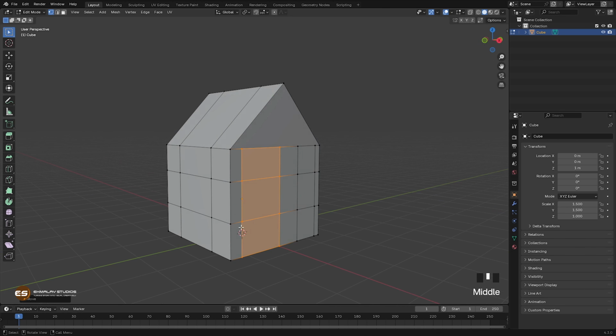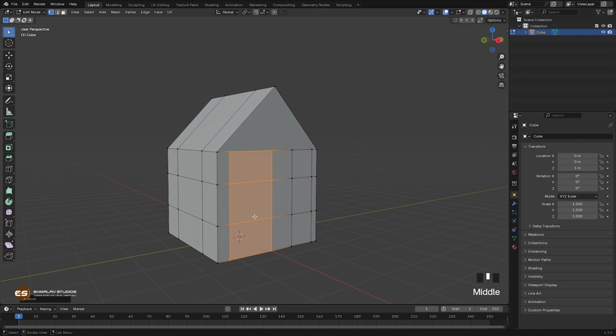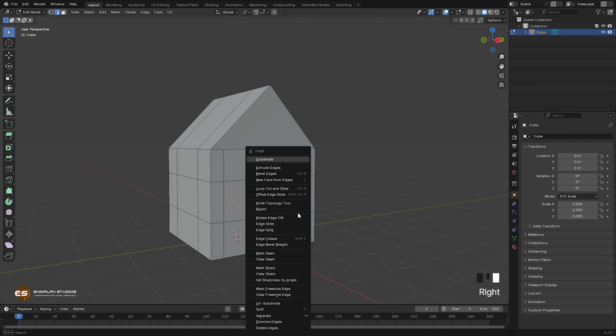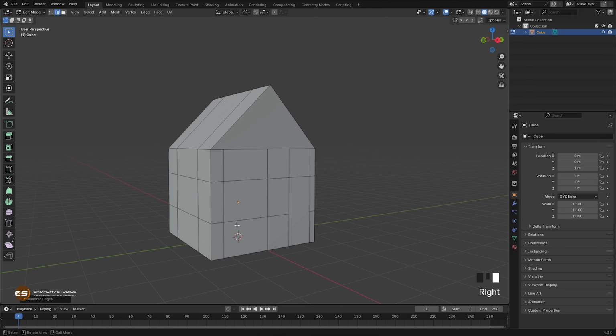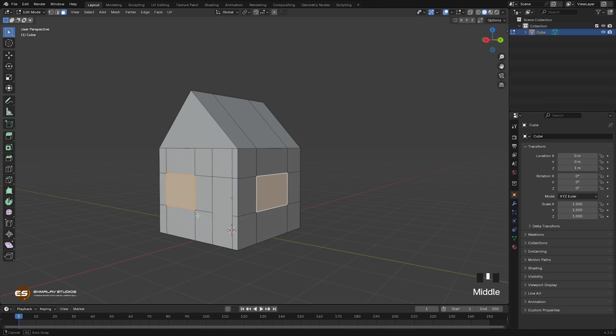So basically we cut our windows and the door. Let's extrude them. So first press 2 to go in select edge mode. You can see the change from here. Select this edge, we don't want this one. Right click and dissolve this one. So now press 3 to go in select face mode and change from here, just reminding you, sorry. And hold down Shift, select this one as well and this one.